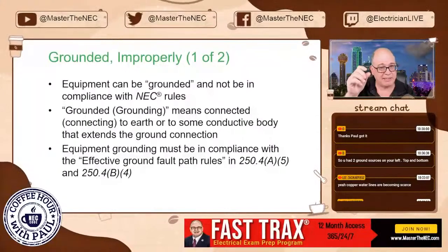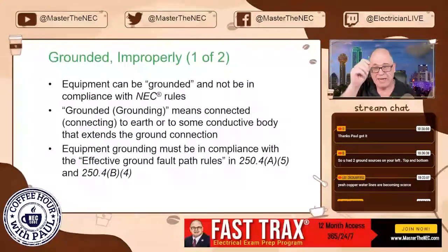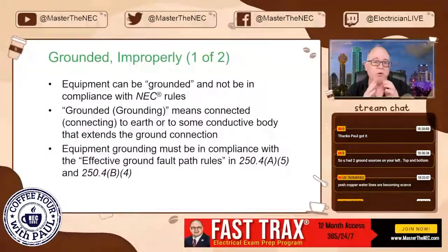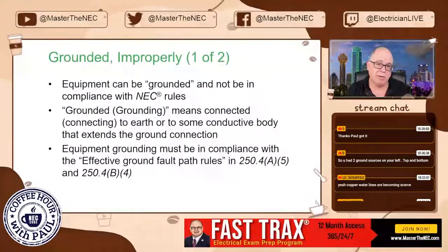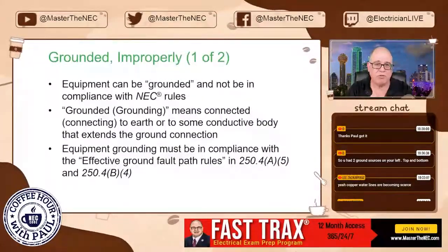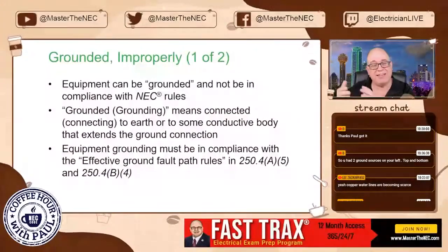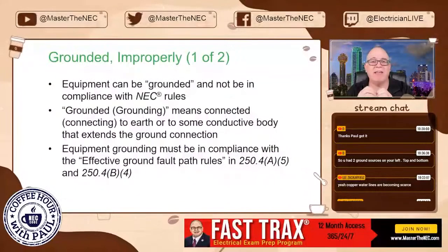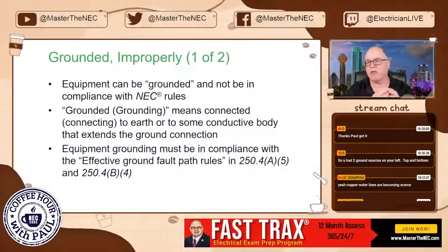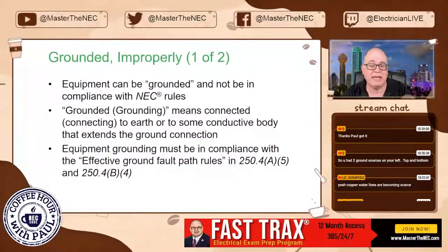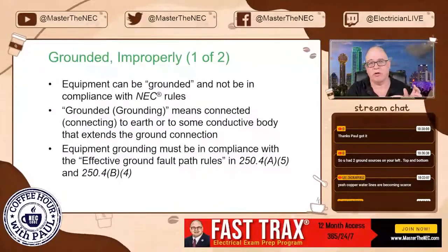You're not. You're going to connect it to the equipment ground. You're going to make it to there. It's unnecessary. So even if you didn't run an equipment ground to a light pole, some people will still say, but isn't it grounded? Yes, because it is connected to earth at the light pole, but it's improper because you're required to run an equipment grounding conductor with the circuit, and that's what's going to clear your overcurrent device.